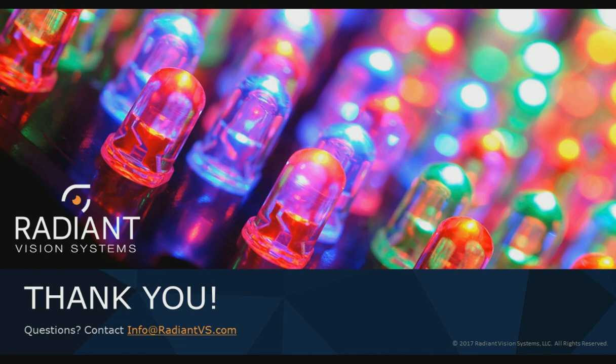Yeah, absolutely. So where it all starts is the luminance measurement of the source. Essentially, the camera measurements themselves are measuring luminance and color spatially over the source, and color in the case that you're using a colorimeter. Then each measurement is looked at on a global perspective to give you an intensity value. After all of the intensity images compile, a total flux calculation takes place in order to give you the total output metric.